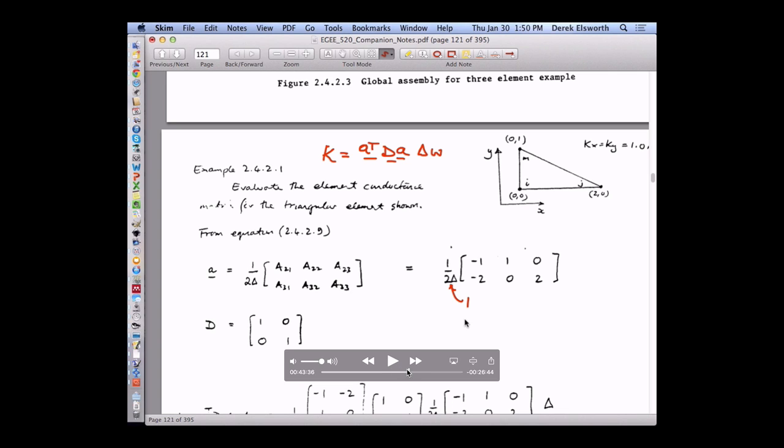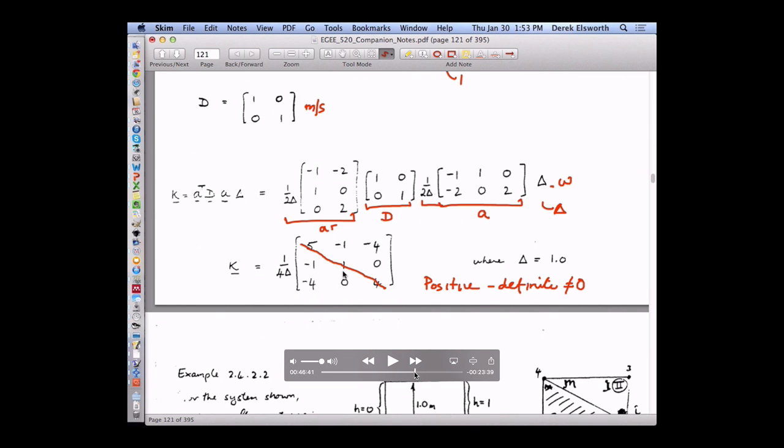And there are a couple of examples which, first of all, cemented, hopefully, the magnitude of the conductance matrix, and noted a couple of things about that conductance matrix. And those were that, one, it's symmetric, it's positive definite. And so if you look at the components above or below the leading diagonal, they are symmetrically disposed about that. It's positive definite in that all the terms on the leading diagonal are non-zero and positive. Positive and definite means that they're positive values, and definite just means non-zero.